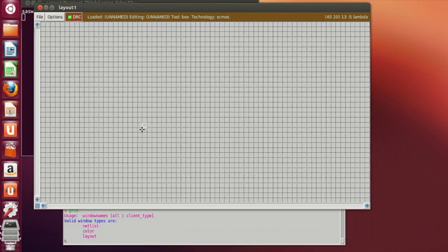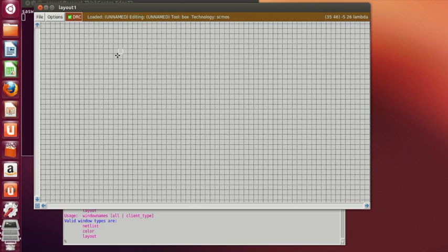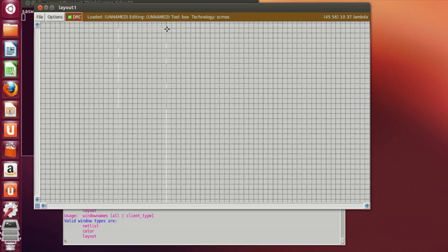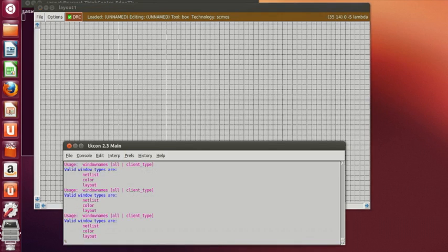Now in the NOR gate, the PMOS are placed in series and the NMOS are placed in parallel. So in order to draw the PMOS, select the area. Since there will be two PMOS in series, we have to select a larger area. Then type paint nwell.